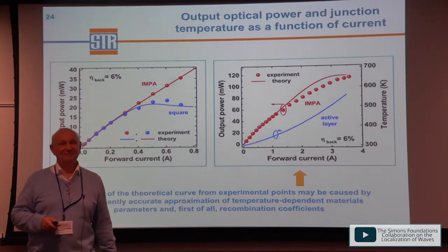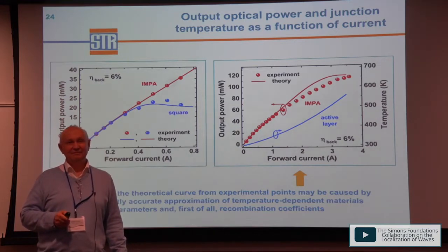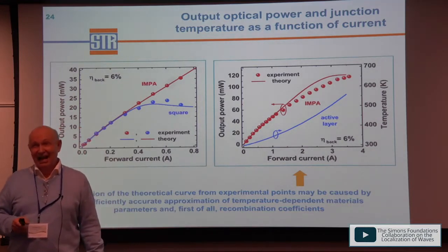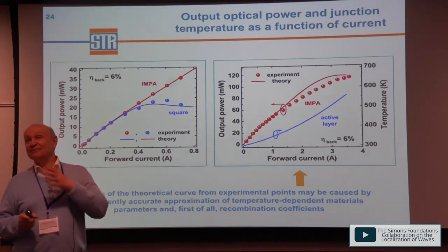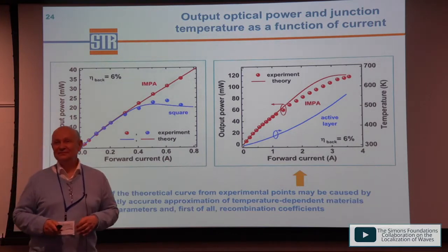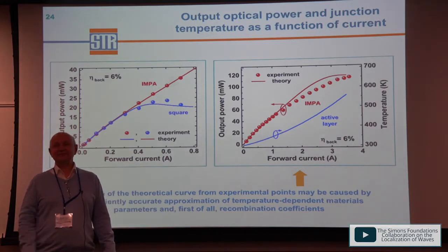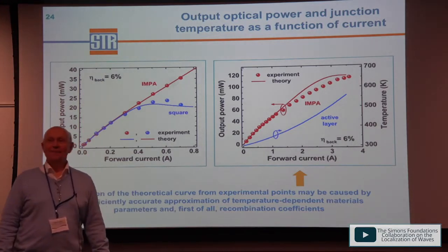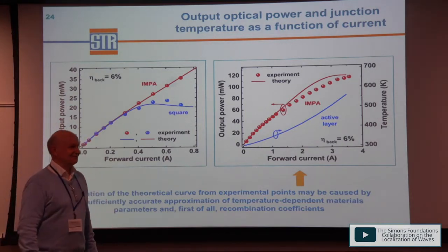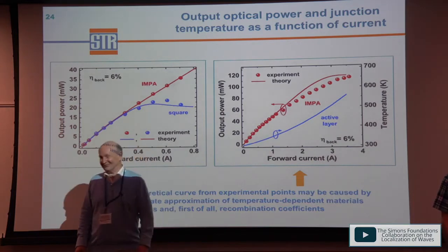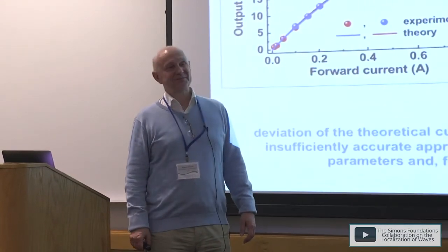multiple quantum well. Presumably it would have a lower drive voltage, but every quantum well presumably produces some sort of barrier. Again, in conventional material system, the barriers are not very clear. In aspects, you want to limit the number of quantum wells for various reasons, because there is a voltage penalty